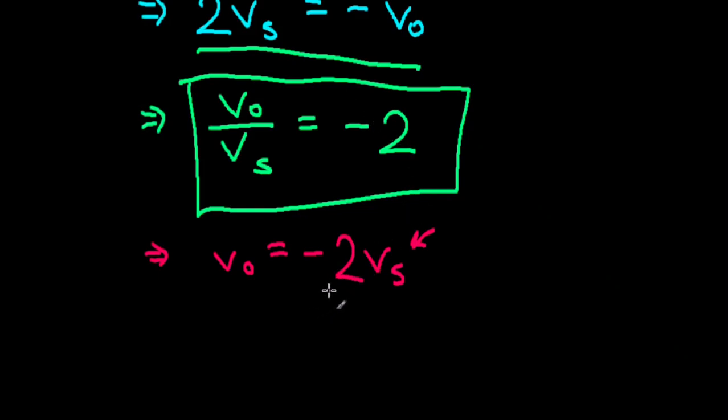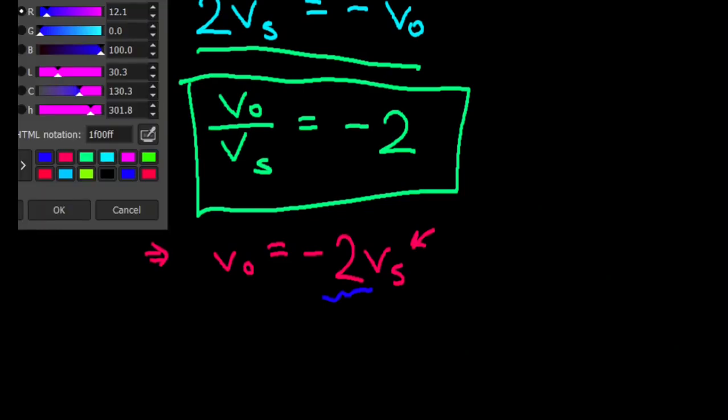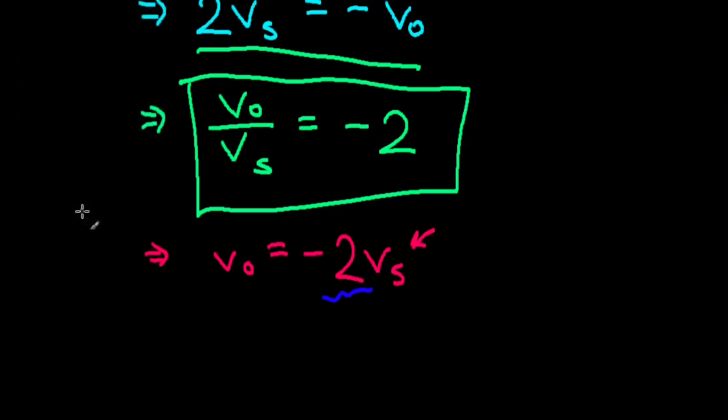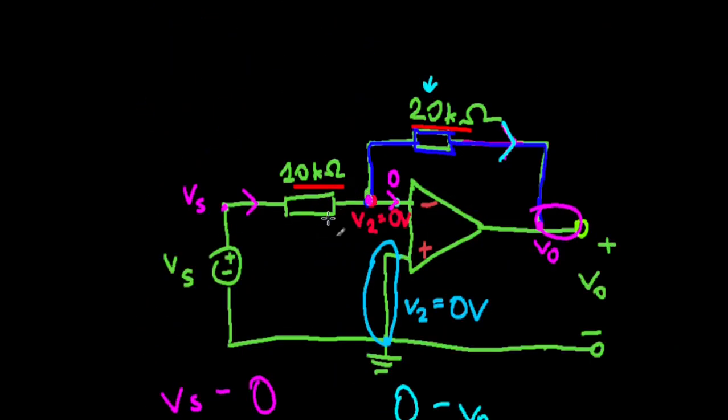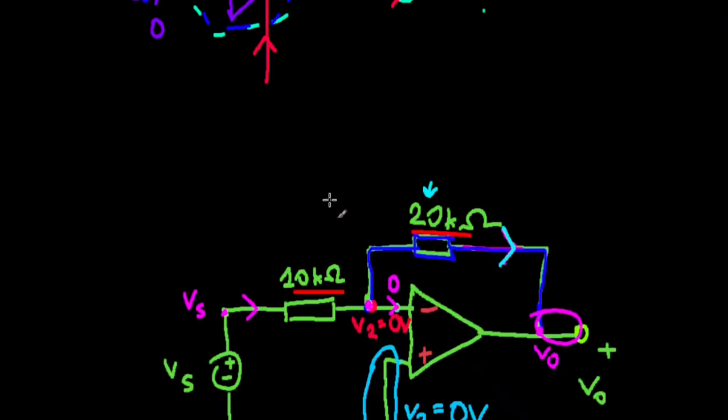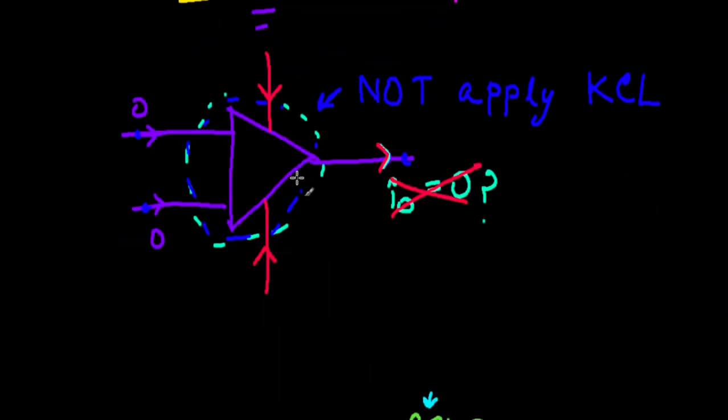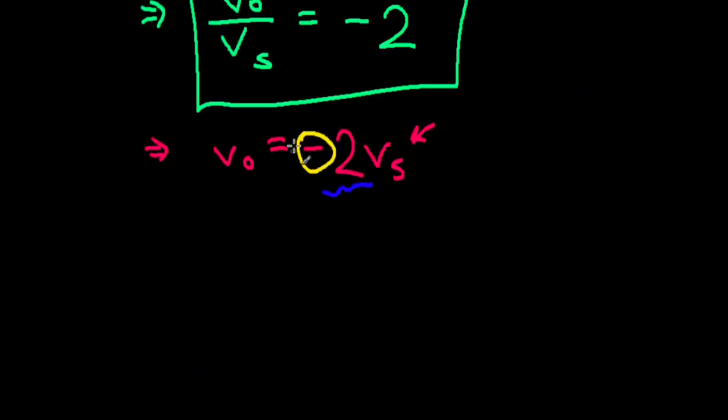So here two things are happening. The amplitude, or I guess I should say size, of this is multiplied by 2, right? So it's amplified, that's one thing. But also, equally importantly, the polarity is reversed. So you have a negative sign here, or you could say, the way we have been calling this for op-amps, the inverting inputs, because we make it negative before calculating the voltage differential. So same thing here. This is basically inverting your supply, right?